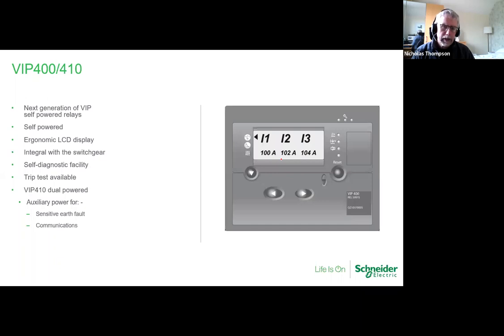Moved on to this one, it's giving you a little bit more benefits over the previous one, where you can see what load you've got on your circuit. You've got more flexibility. You can set it down to an amp, and you can actually do what we call sensitive earth faults. So anything that you need below, say, 2 amps earth fault protection, then you're going to need to use what's called sensitive earth fault protection, and I'll cover that in another slide as well.